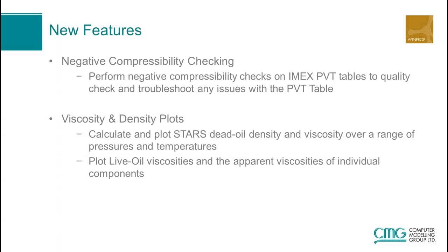For those of you that are unaware of the methodology of STARS, when you input gas properties, for instance, you're actually inputting them as an apparent liquid viscosity and density of the gas property, not just the straight gas phase viscosity. So you can plot those in WinProp now to get a firmer understanding of your PVT before moving into STARS.